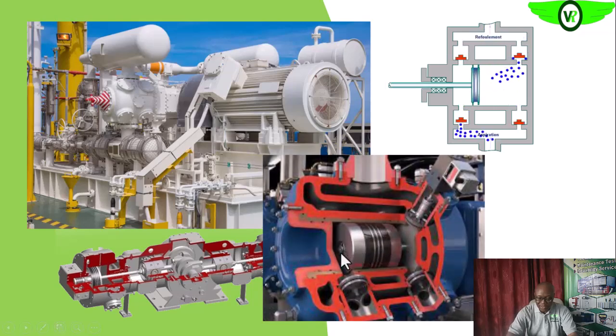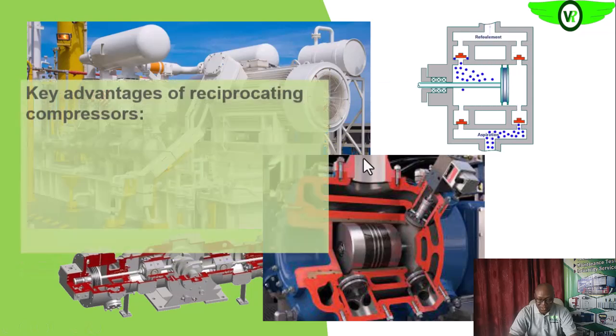You see the piston as it's moving away, here opens up, admits air, then compresses, and then it is discharged. Then here too opens up as the piston is moving away, moving this direction. Then as it's returning back, it compresses the air, and then here opens up, it is also discharged. So that's the double acting reciprocating compressor.